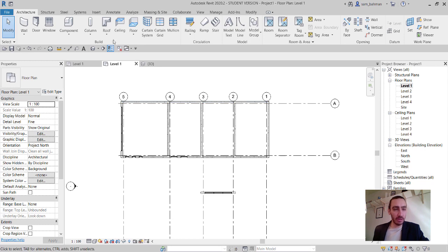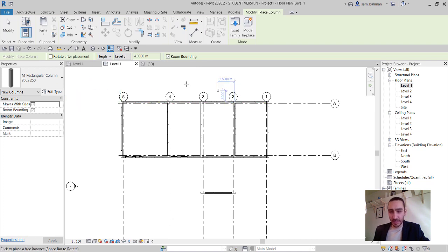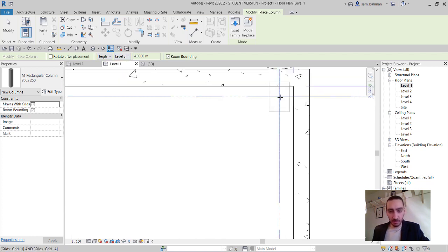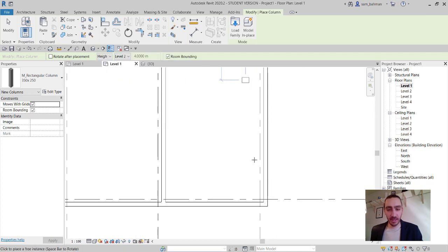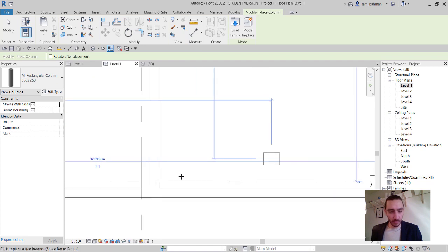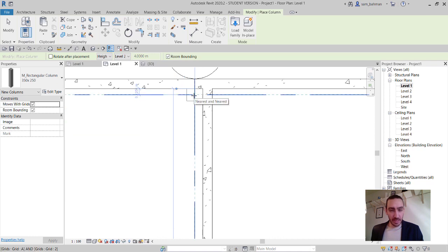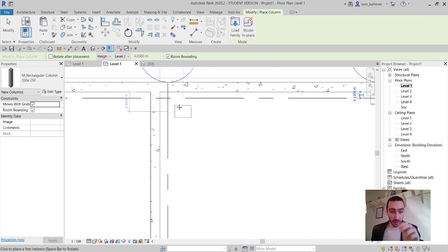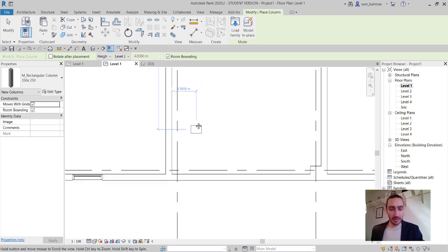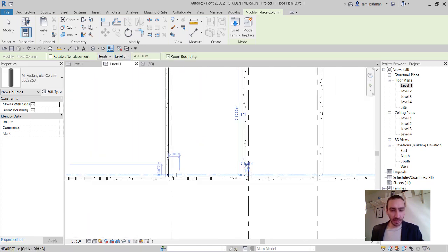Now it's time to place the architectural columns. Simply go to the architectural column, choose it, and make sure it's only from its own height and from level 2, since we're on level 1, and then you can put this column. In order to rotate the column, simply press space. As you can see, it's perfectly getting done there. The snap is there. I simply bring the point viewer onto the cross section of the grid lines and automatically the columns get placed there.